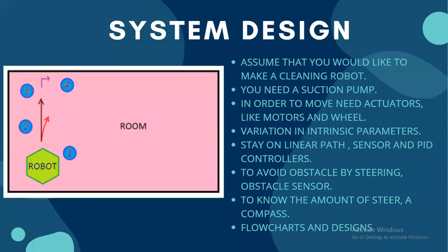So a working robotic system should have RANSAC, random sample consensus, an algorithm that avoids unwanted noisy data. Then it should have SLAM, simultaneous localization and mapping. Then definitely it should have a path planning algorithm. That makes your robot what we call an autonomous robot.